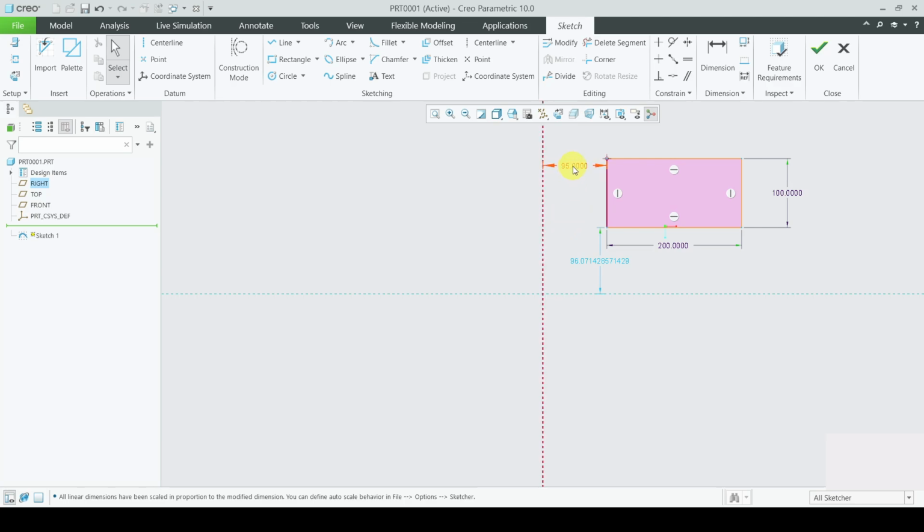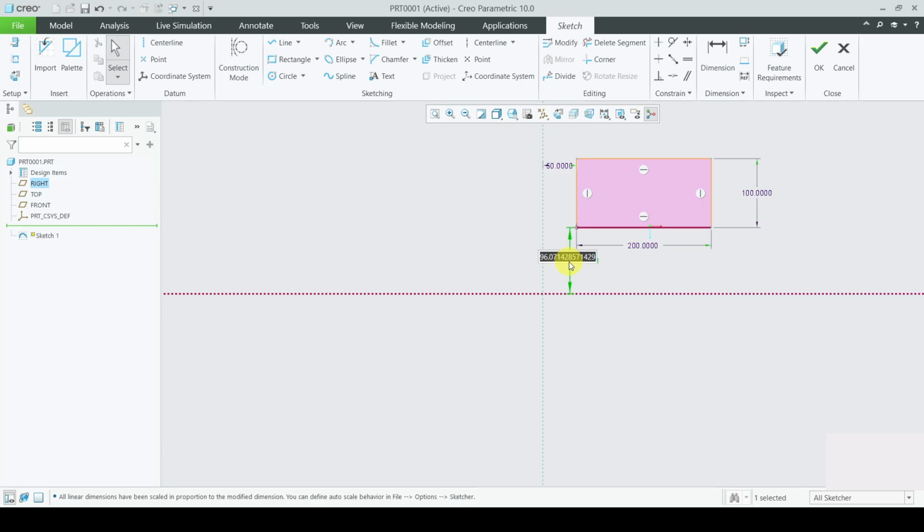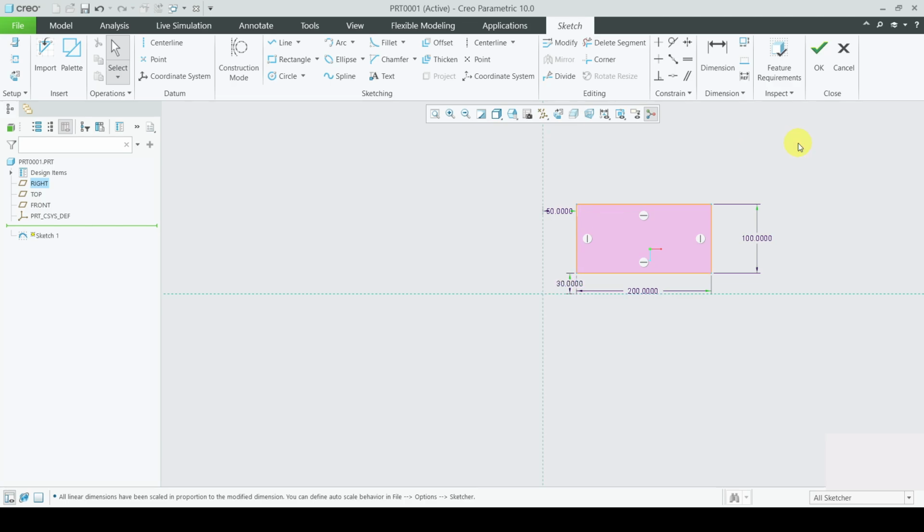Okay, so these two numbers are called references. The earlier ones were dimensions of this rectangle, and in Creo Parametric, these two numbers are called the references of this rectangle in order to create your sketch. So you can set it to be, say, 50. You will double click, the editor will open, you will write 50 using the keyboard and press enter. Okay, and you can set this one as well as maybe 30. Okay, so in this way your rectangle has been created.